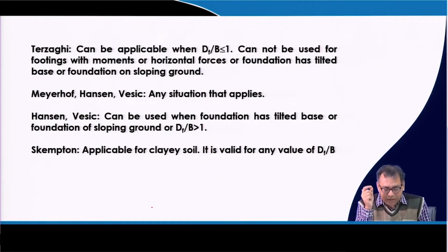In general, the Meyerhof, Hansen and Vesic, these three equations can be used more or less for all purposes. That is why these three equations are very commonly used or famous, because they can be used for more or less all the cases, except the Meyerhof equation you cannot use if there is a tilting base condition, because that is not recommended. Otherwise, Meyerhof has suggested for sloping ground and all the other cases also, inclined footing, if there is a movement, and then you can use that. So, that means the Meyerhof, Vesic and Hansen you can use for all the conditions.